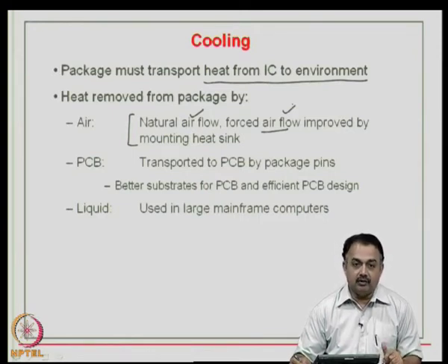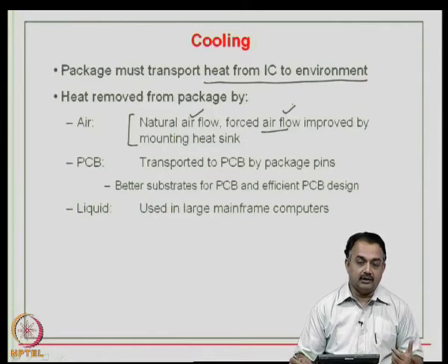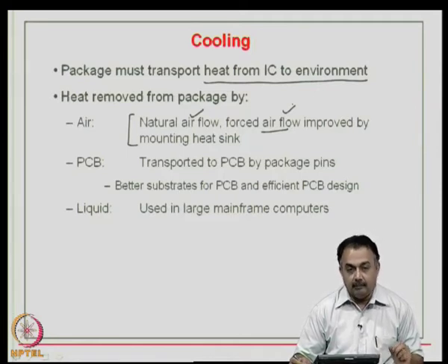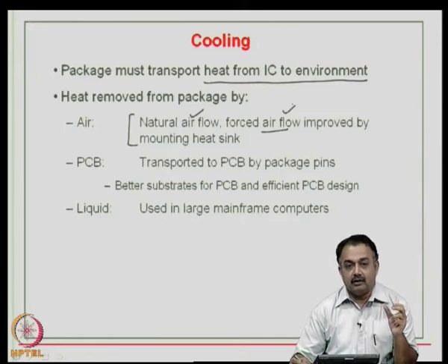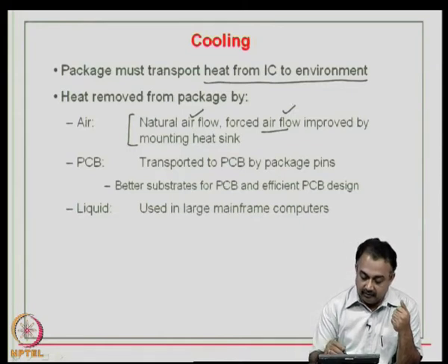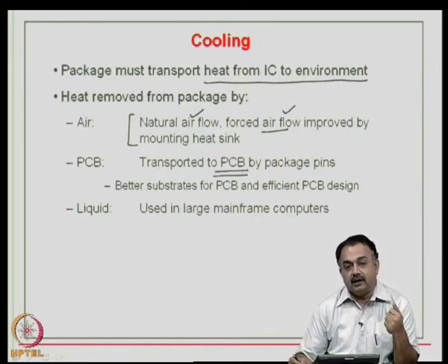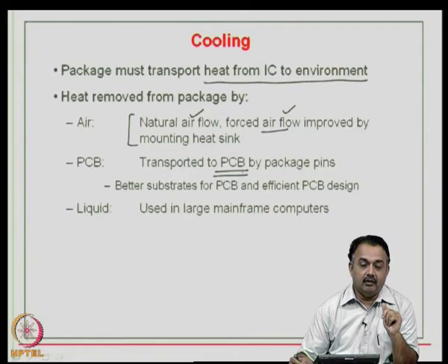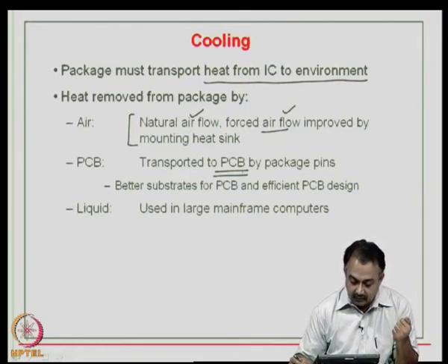Now, the printed circuit board or the PCB on which the components are mounted, on which the packages are mounted, will also have to behave as a heat sink. Therefore, the package pins, the leads or the solder balls in the case of a BGA or a CSP will have to transport this heat to the PCB, okay, so that the heat at the die stage is quickly moving through the package substrate, through the package pins, and then to the PCB on which the host of components are assembled or mounted.